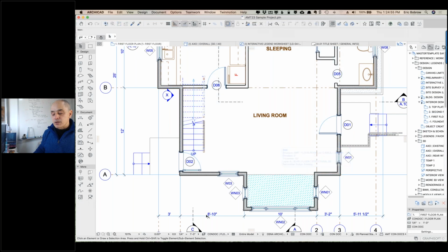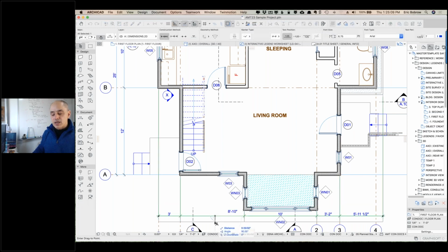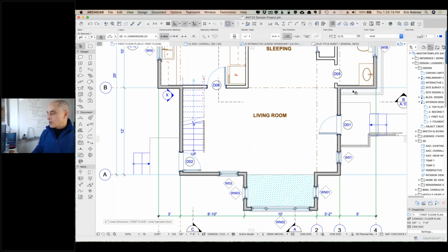So I'm not quite sure what options there are in AutoCAD in terms of editing a dimension by grips, but we can grab individual parts of a dimension, like, for example, this measurement, and move it into position. Sometimes you need to move it to get it around other annotation, etc. And you can, of course, just move the entire dimension in or out, and everything moves along with it. So let me just undo those here, but I do appreciate these questions, and hopefully I'm hitting some interesting points along the way.